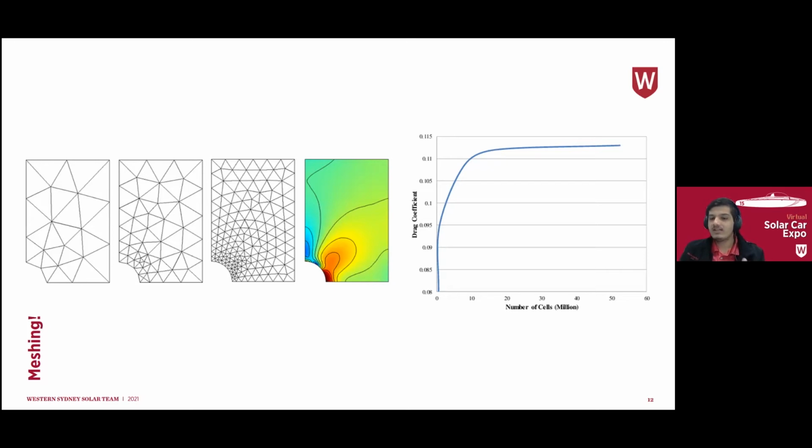The second important thing is the density. The finer of a mesh you have, the more detail you'll be able to see in the results. You'll be able to differentiate the conditions at different locations with more granularity, and you'll be able to capture smaller disturbances. You'll be able to capture disturbances caused by smaller features more easily, especially in CFD. However, there is a compromise in this. The finer your mesh, the more computational resources it takes to run the simulation.